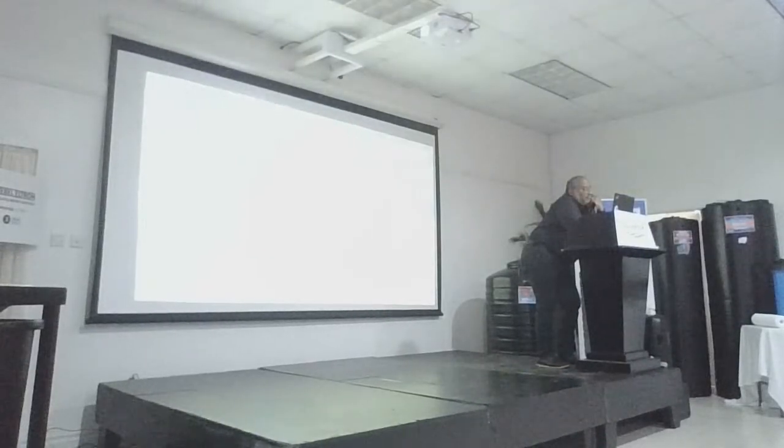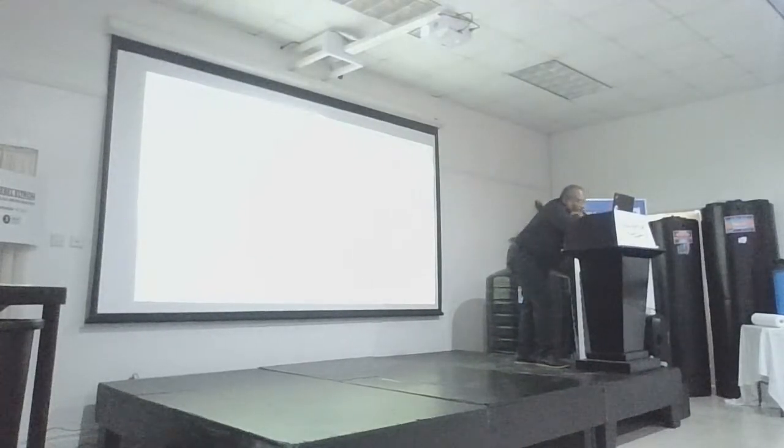Step 1. Inspection. Every 12 to 18 months, or as required, the tank should be checked to determine the depth of both the scum and sludge. In a low-profile tank, the scum should not exceed 3 inches and sludge should not exceed 10 inches. In addition, if the wastewater level is too high or too low, it is a clear sign of malfunction.